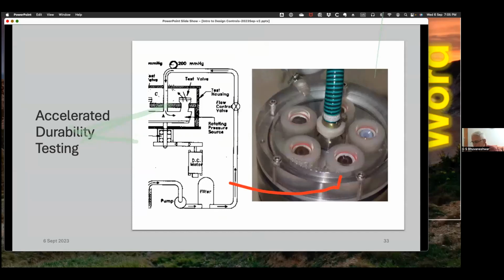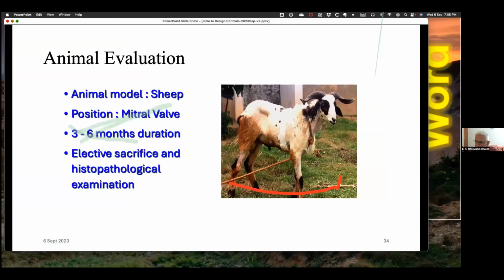And the third one was the durability test, where we were cycling the valves at 700 times a minute, about 10 times the acceleration of the normal cycling at 70 times a minute. So that in about 1 year of non-stop running, we could get the equivalent of 10 years of closing of the valve. This is again our model, I think our Mark 3 model of our test system. The first one was really bad. It was leaking all over the place. Model 2 really worked well, and this is model 3. So a lot of development went into that.